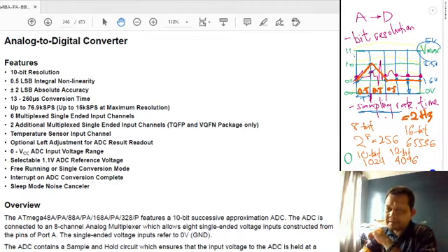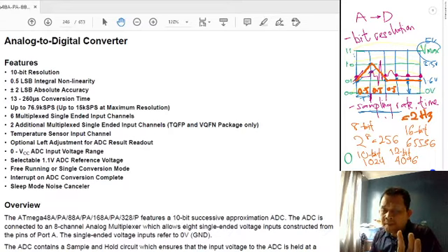The one we see here on the screen now is the result of quantization errors. So how much do you allow? Of course you can have 1 trillion bit, 1000 bit resolution. But the thing is, the more bits you have, the more memory you need to store your digitized values. Remember, the more resolution bits you have, the more memory you are going to need.